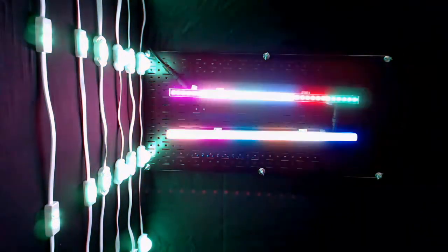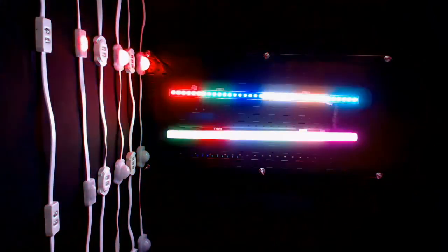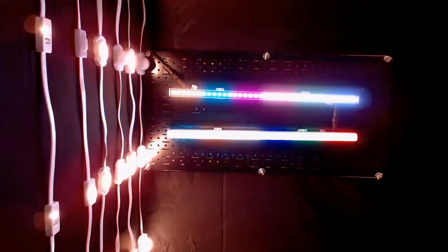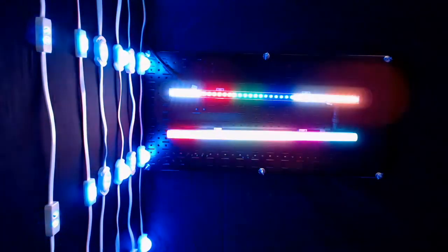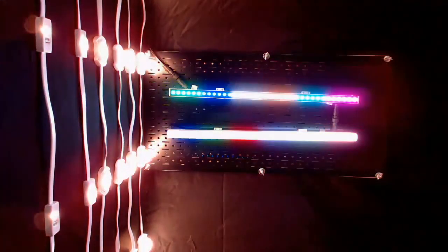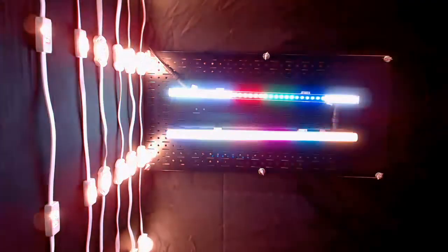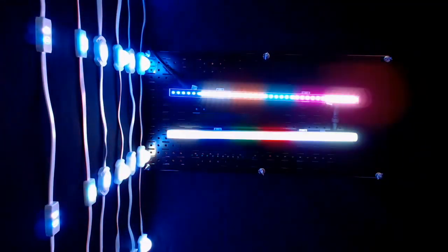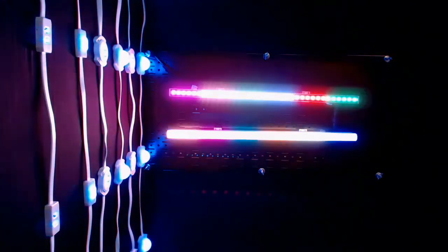While we're waiting, I think some eagle-eyed viewers may have noticed you can order the dot product with modified dot spacing. But whenever possible, we do recommend using those standard 6 and 12-inch pitches, and then just pulling in a little bit of slack if you need, say, a 7.5-inch. Just bundling up that cable in between nodes when possible, because that will be easier from a long-term maintenance standpoint, and we do require higher MOQs for those dot pitch variations.